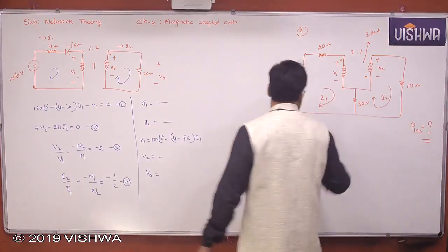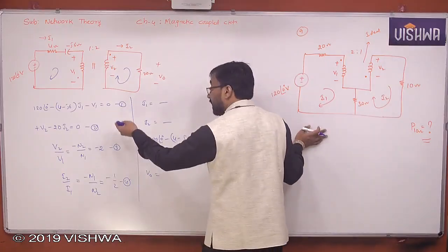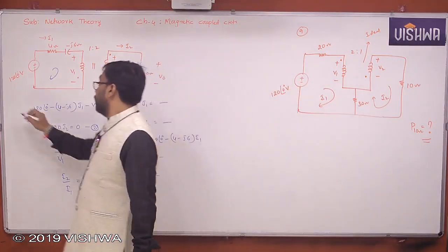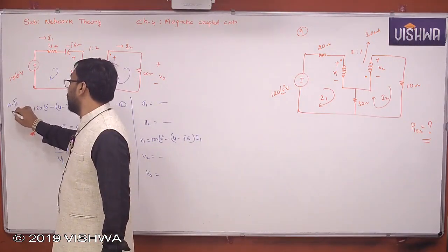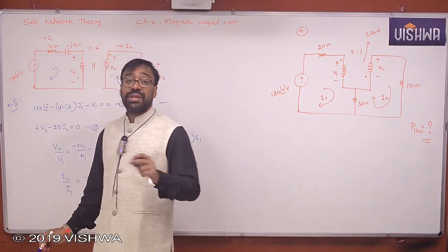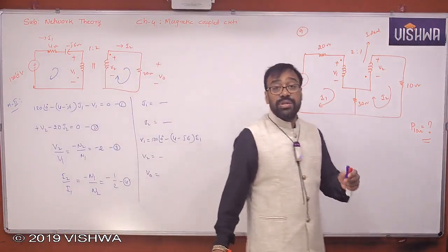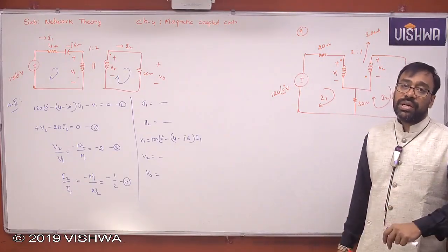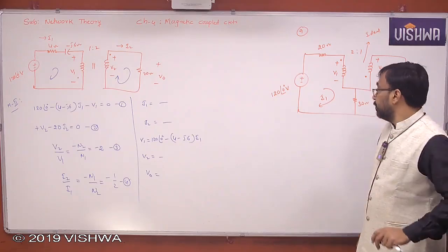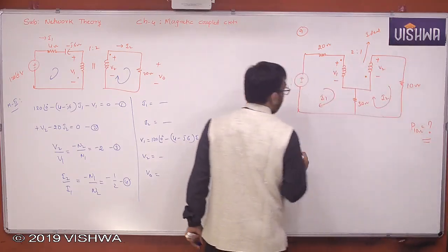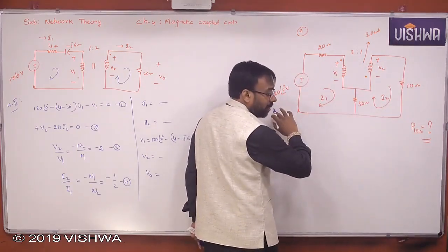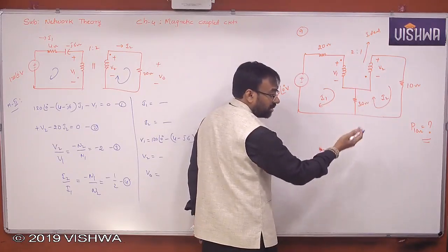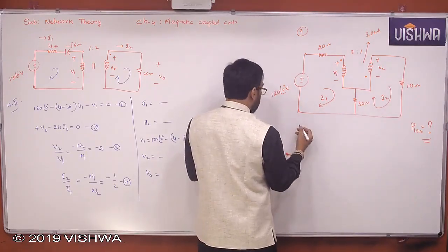Okay, so in such cases, we can use the second method, method 2, right? What is method 2? Simply writing the equations and finding the relation between the two transformers, voltages and currents, and then obtain the equations and eliminate whatever is unwanted. Try to get the solution. So this I will apply in the same way. I can't really apply the refer to secondary concept here. Therefore, look at this now.